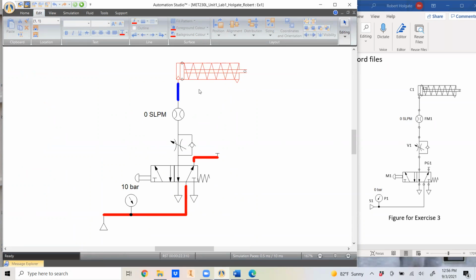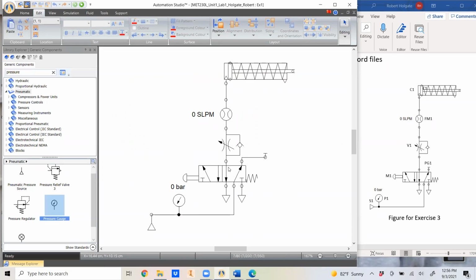Okay, so what we can do here, let's stop the simulation, is change the operation of our M1 device. Our M1 is a 5-port, two-way, two-position flow DCV, directional control valve, but it's normally closed, meaning the spring applies a force on the right side of our diagram, so it normally sits on this box on the right. That's closed because the air line comes in, crosses over, and is plugged. So we made it normally closed by adding this plug in here.